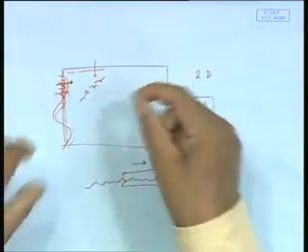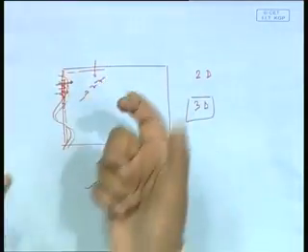In tomorrow's class we will find the response in the 3D spectrum, which is nothing but one more level of algebra. Here I have added all the omegas and responses in the omega direction. There I have to repeat that in the theta direction. Here I have one piece of paper with omega, and there I have to do each piece of paper for one theta, 10 pieces, and add them together. It is just one level of algebra, so there is no thinking involved. But still, having said 2D is useful, because 2D usually, but not always, gives a larger response, and a more conservative design comes out of that.